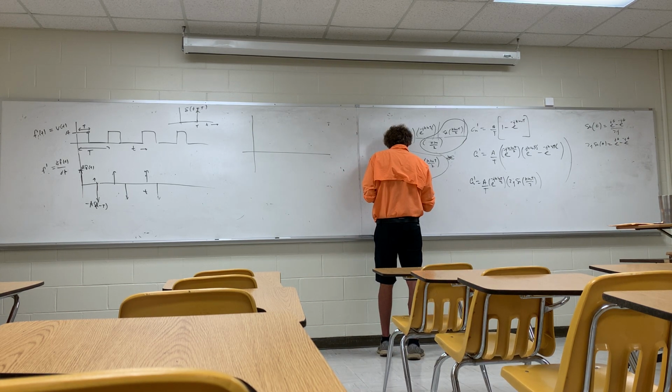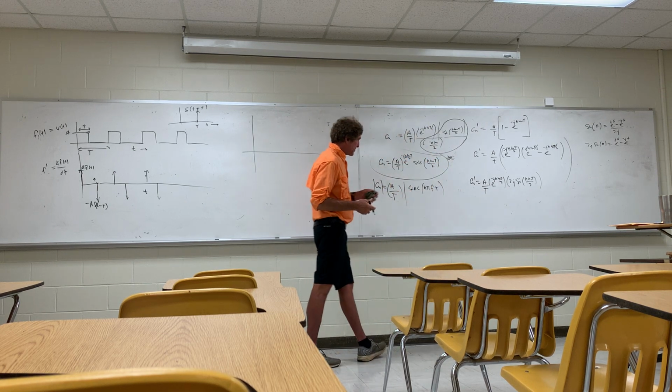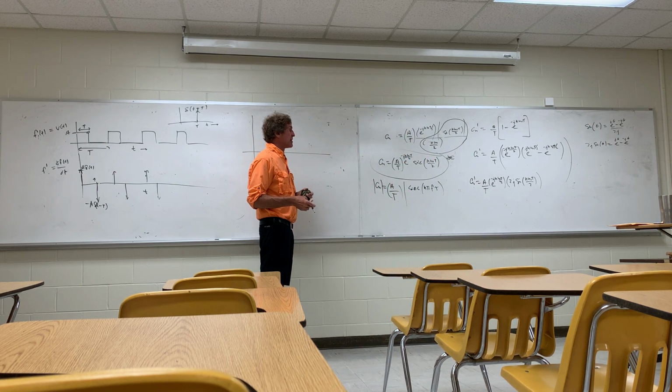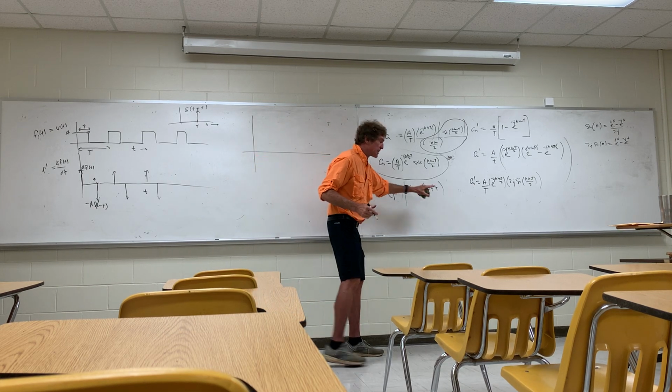And that would be times the magnitude of the sinc, S-I-N-C. Omega naught here is 2 pi f, so it would be the sinc of n times pi times f times tau. If you replaced omega naught by 2 pi f, the 2's would cancel, you'd have a pi in there. And now this is versus just frequency.